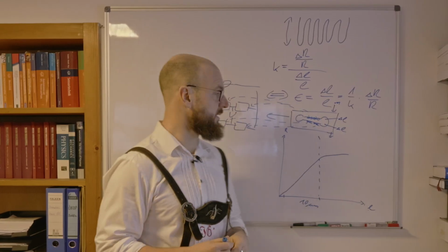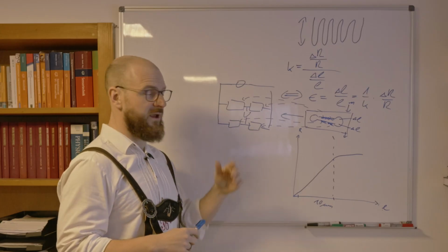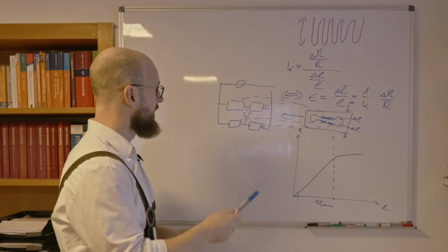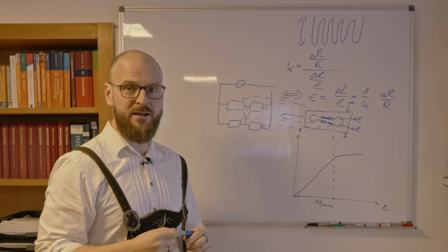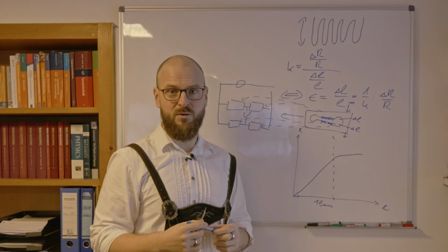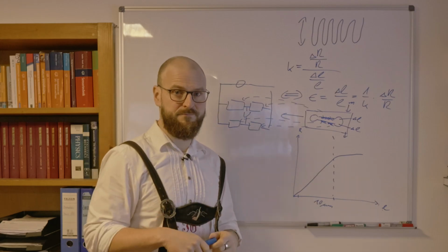The first possibility is to use those temperature compensations within the measurement bridges. Remembering the chapter on measurement bridges, we realize we can place the strain gauges in a certain way so the temperature influence of the resistance would be in the denominator and therefore very small.